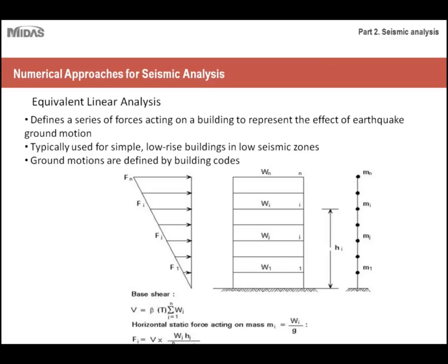So first, I'll talk about the most basic type of seismic analysis that's available, and it's called equivalent linear analysis. That's a good way to remind yourself of these different models. Equivalent linear corresponds to your equivalent linear constitutive model for soil. Essentially, this is the most straightforward and simple seismic analysis type, and it's used